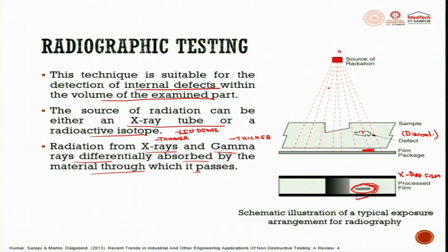There are different types of radiography that we can classify. These are computed radiography, meaning the CR technique, which is a transition technology where film and digital radiography are both partially involved. This uses a reusable, flexible, photostimulable phosphor plate, which is loaded into a cassette and exposed in a manner similar to traditional radiography film.